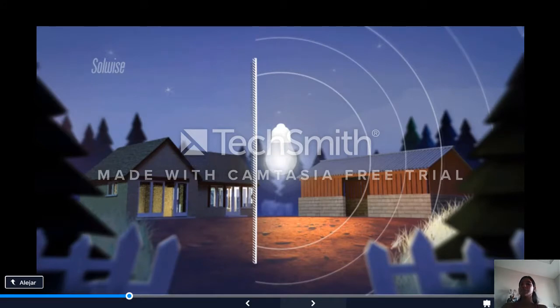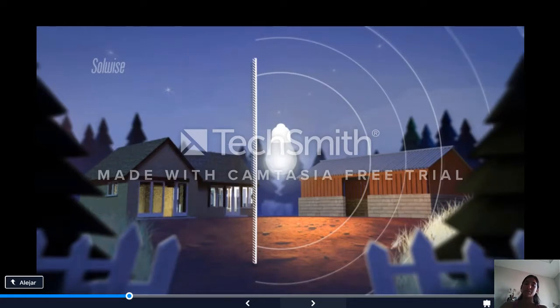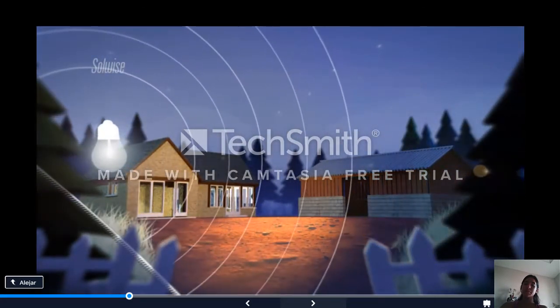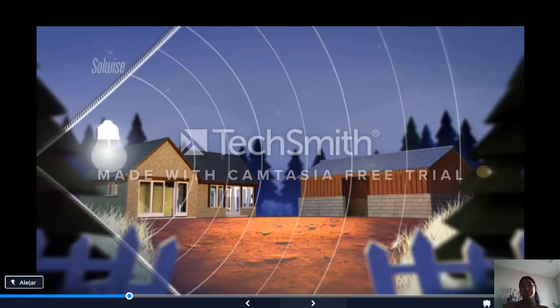We've achieved this doubling of the signal by giving our antenna some gain. We express this gain as 3 dBi. The 3 dB simply represents a factor of 2, and the i tells us that the gain is expressed by comparison to the isotropic condition. We can take this further. Bringing down another mirror to form a corner would give us yet more gain. The light is all going out into a quarter of the sphere now, so we have an EIRP of 4 watts from our original 1 watt signal, achieved using an antenna with a gain of 6 dBi.